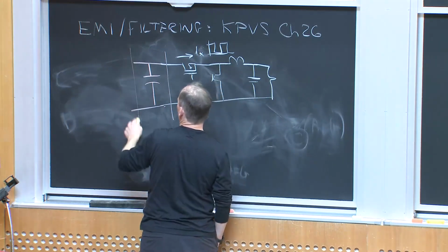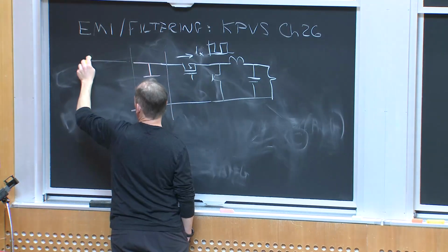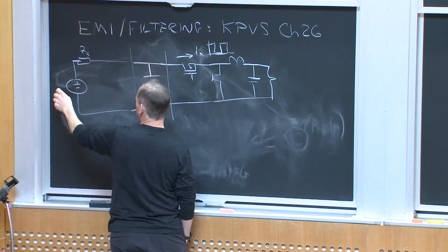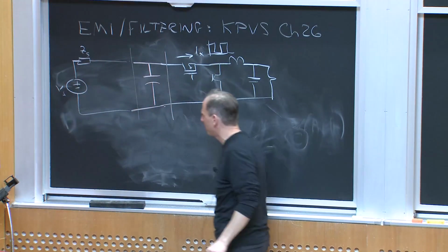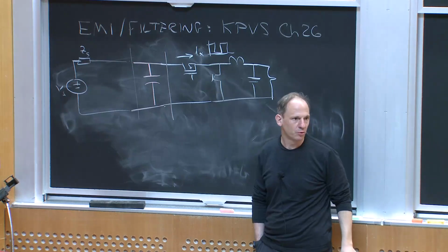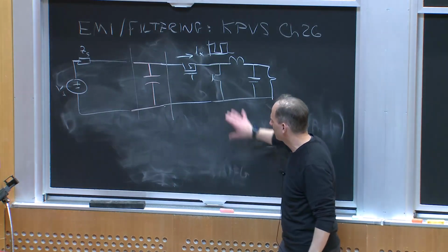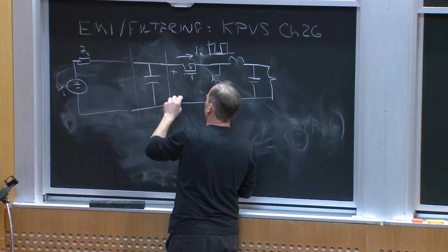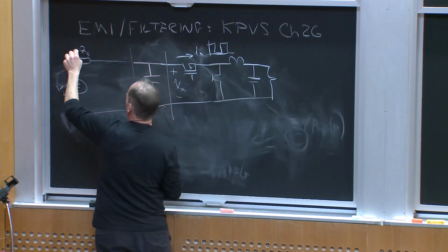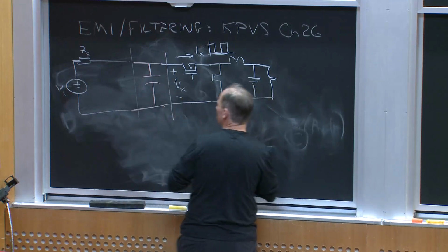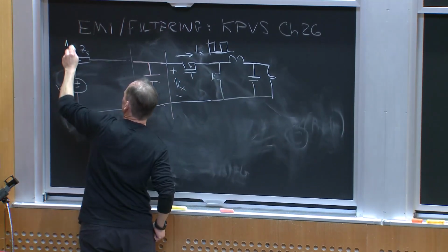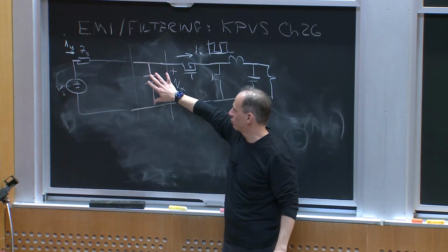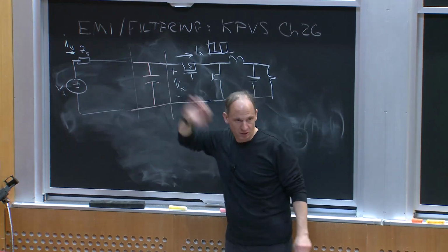And we said, well, if I just connected this up to some voltage source, V sub S, with a source impedance, Z sub S, I would probably run into trouble with repeatability because depending upon what Z sub S looked like, I would get different voltages Vx, and maybe I'll call this current I sub Y, on the other side of the filter. And so it's kind of problematic from a repeatability point of view.